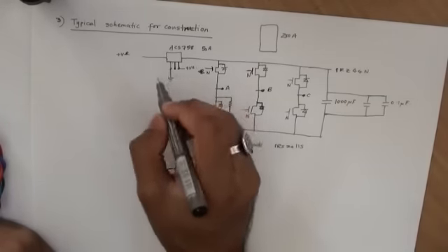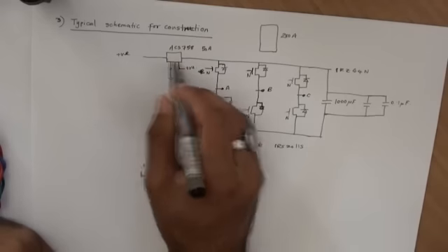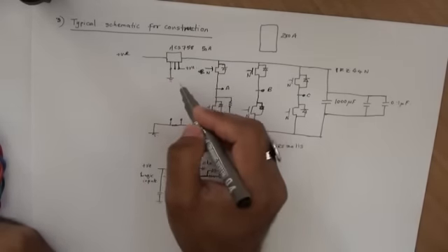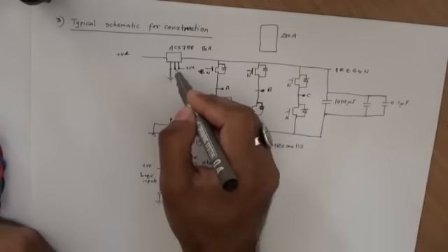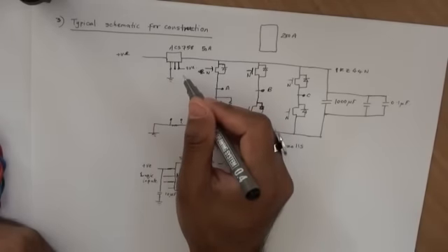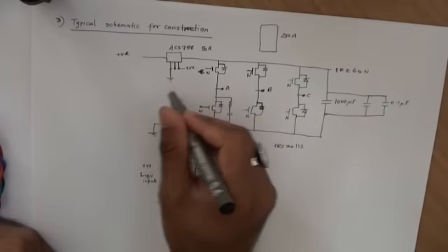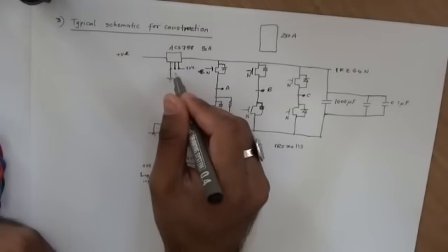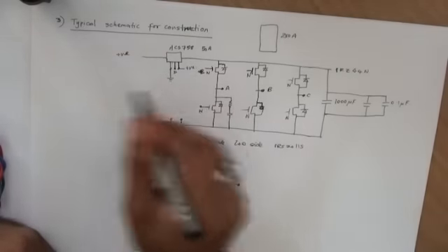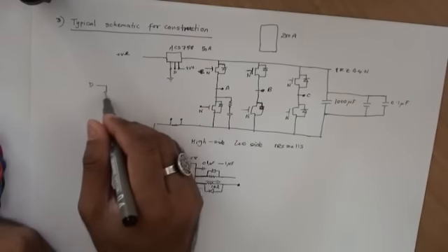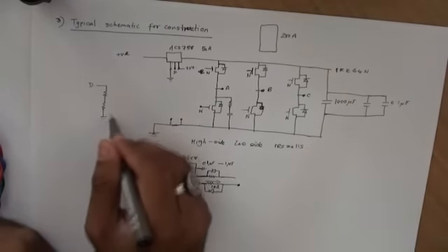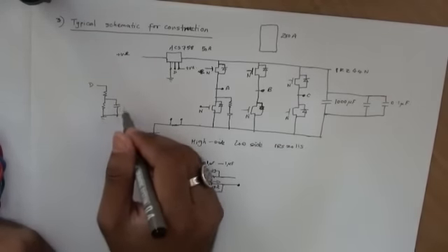And that's proportional to the supply and the current that's passing through. So it's a ratiometric output. This output here, you ideally want to voltage divide. So if this was your D, to voltage divide that to ground with a filter cap. Never forget these filter caps.